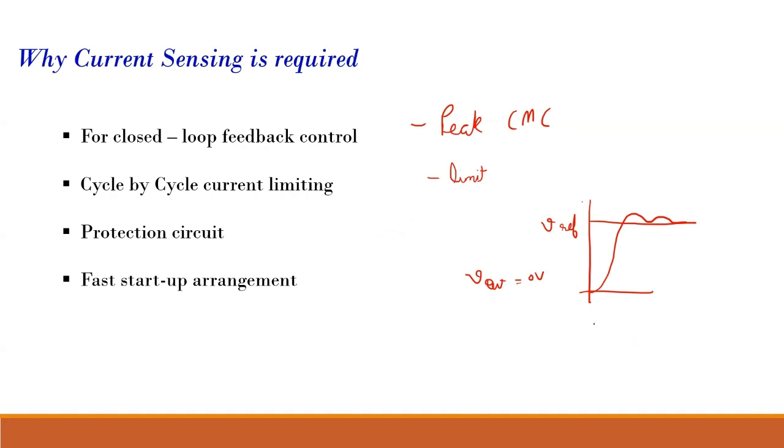What would happen usually is we have a capacitor with VC of 0 equal to 0. If a large amount of current comes through this resistor, it will directly flow through the capacitor, and the capacitor will act as a short circuit. So we would want to limit the current in the startup time. In steady state, this will be like 5 volts or my reference value. But in the initial condition, when we turn on the circuit, this capacitor voltage is at 0 volt.